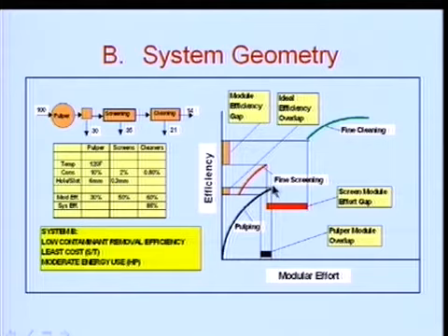Now we say we're not going to do all that we did before, so we're going to have less efficiency in the pulper by increasing the hole size, so that we pass some of that contaminant removal to the screen. But in the meantime, the screen guy has put in 3 millimeter slots in the screen, so the overall efficiency of the screening module has gone down, and the cleaning is the same.